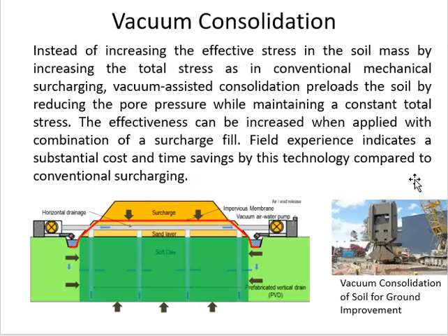So this method can also be used at landfills to extract gas. This method can be more effective when combined with preloading technique. The preloading further enhances the consolidation process when compared with the conventional preloading technique. This vacuum technology reduces the cost and time of the treatment.